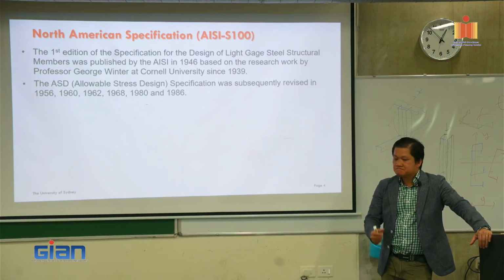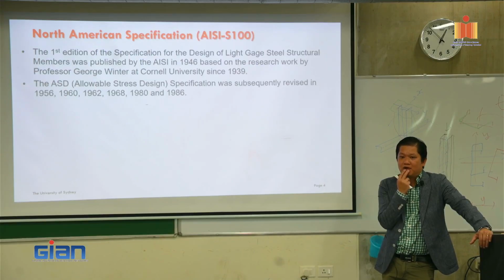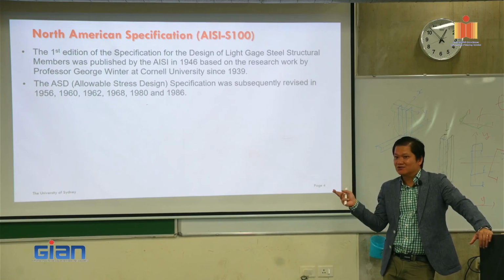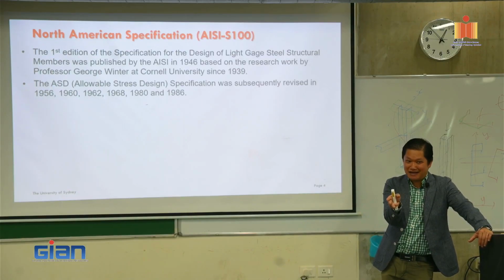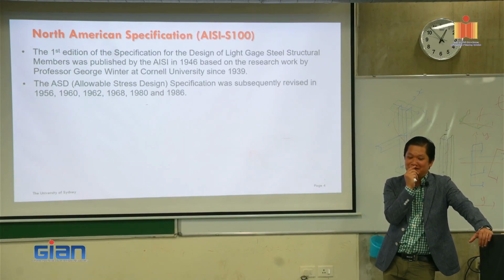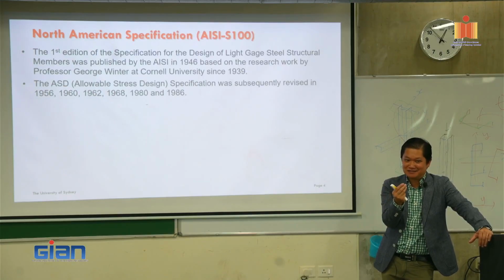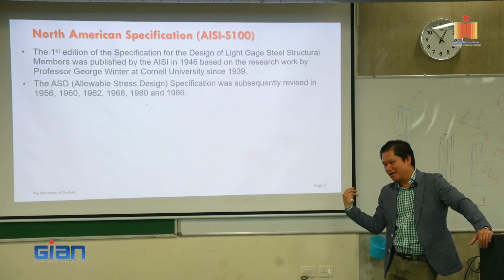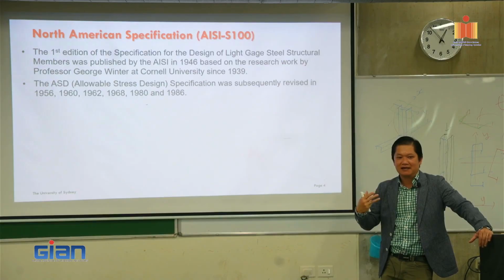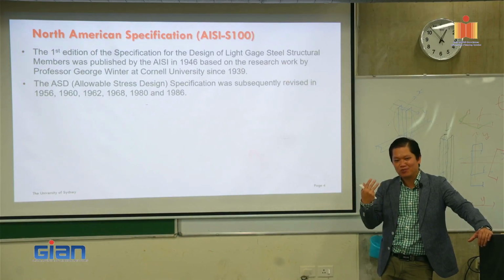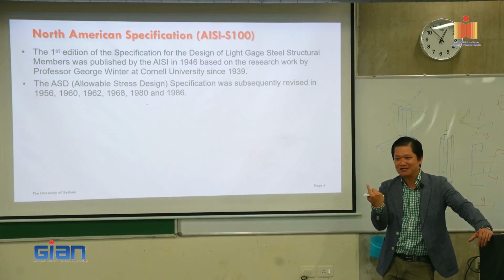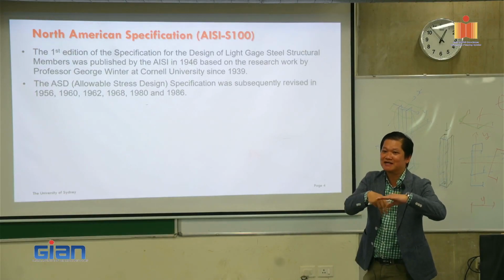In the case of gravity, we assume that the load acts through the centroid. But the channel section is a little bit of a problem. The shear center is offset, so there's another problem coming up as well. So as you say, that is more complicated. But what we decide is simply wind uplift. We assume that the load is wind uplift, so the wind uplift is perpendicular to the principal axis.